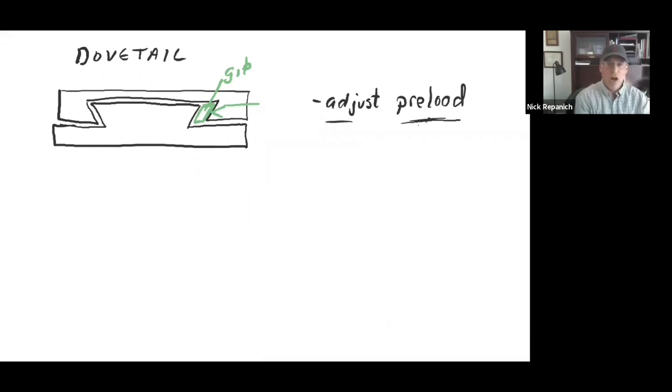This is a pretty common device in, for instance, manual milling machines and drill presses, where you clamp tools together. You can see on the end, this has a hole, and that hole is where you would put in a screw mechanism and set something. Why would you use something like this with the sliding friction? You would generally use it to set a position.